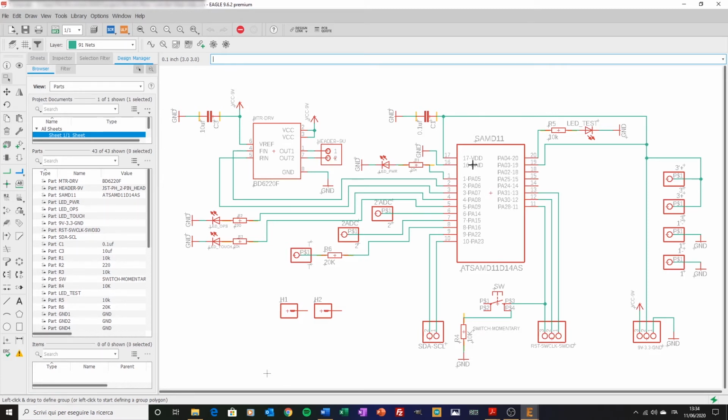Then we have two more lines, 17 and 16. These are the VDD and ground. VDD is connected to an MLCC decoupling capacitor of 0.1 microfarads. To close the MCU view, we have this line, which is PA3. This is the voltage reference for the ADC. And then we have three free pins, which are PA24, 25 and 02, which for the moment are not connected.